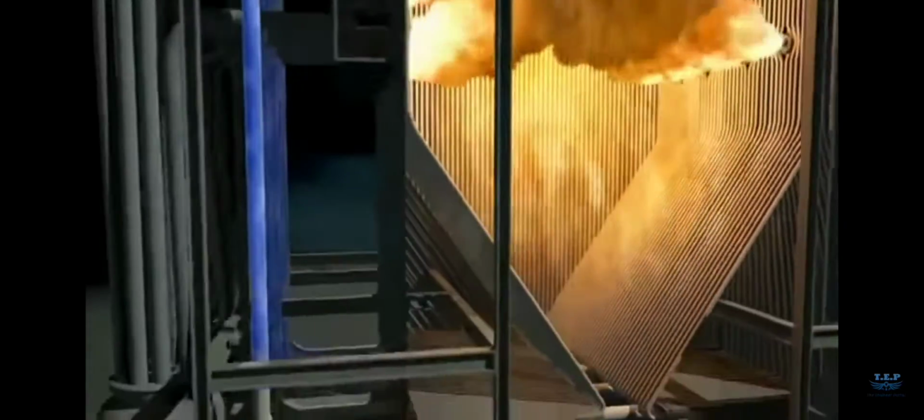Liquid water flows through large downcomers and into the base of the firebox. A network of 2-inch tubes lines the firebox walls, and burners force feed a continuous supply of combustible fuel into the ultra-hot firebox. Eventually, the insides of the firebox burn so hot that its surrounding steel walls would melt if not for the tube-lined walls of liquid water.